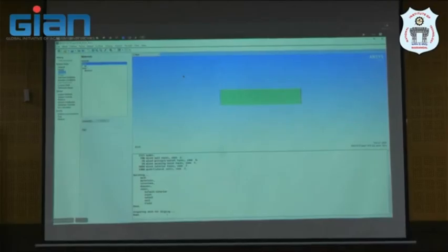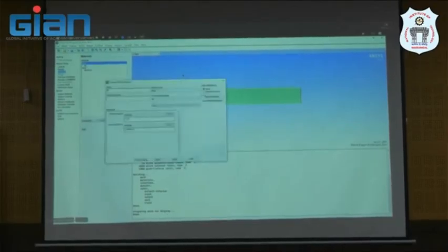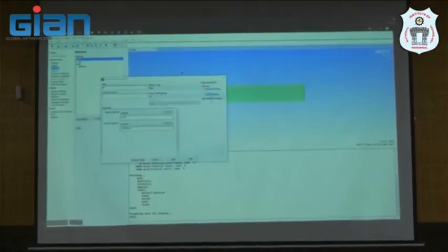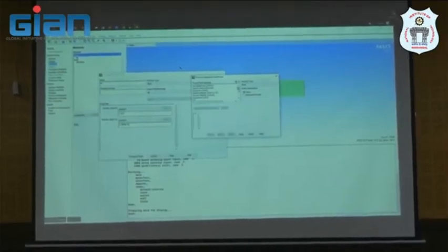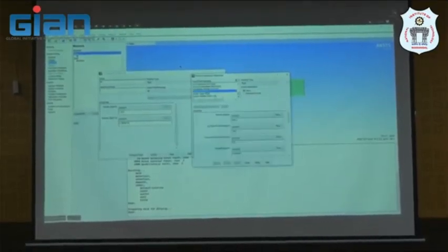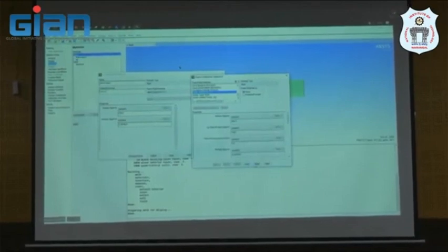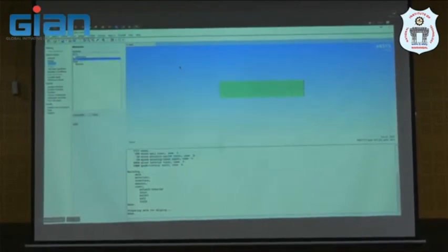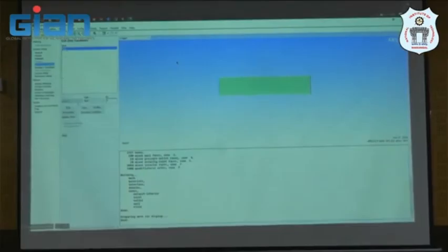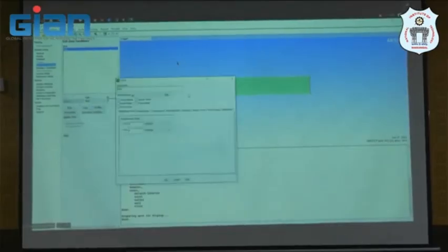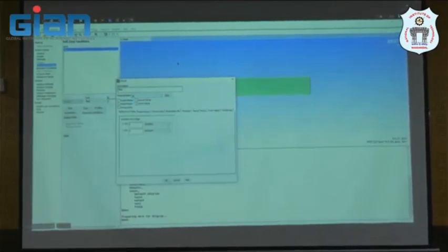Also we can choose some other material. There is a FLUENT database in this software. For example, this one is water, liquid water. In our case it is air. And in this interface, we can change the material such as air or liquid water, but in our simulation it is air, and we keep it as air.